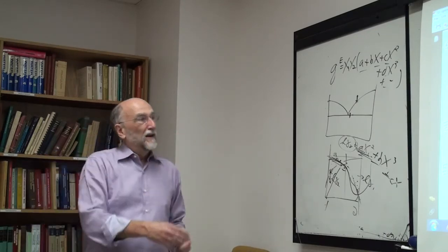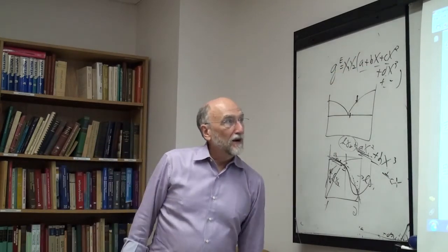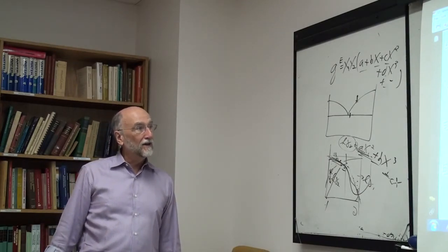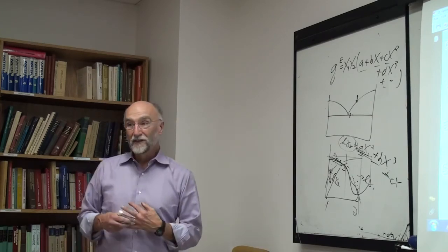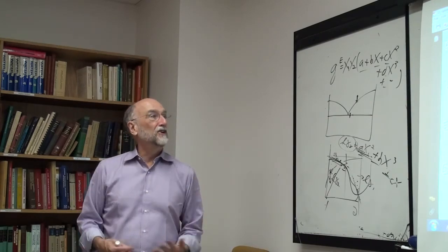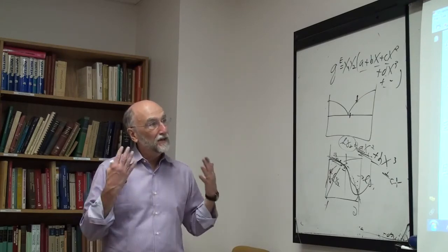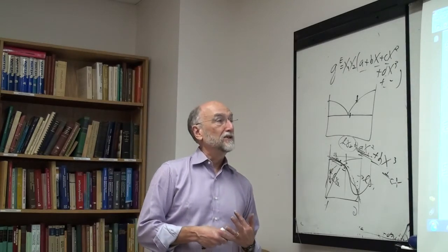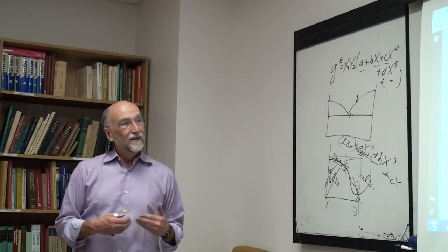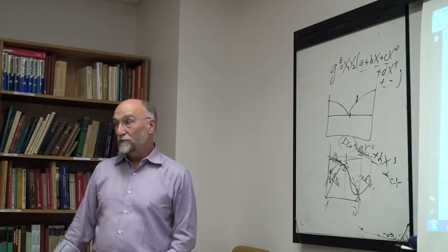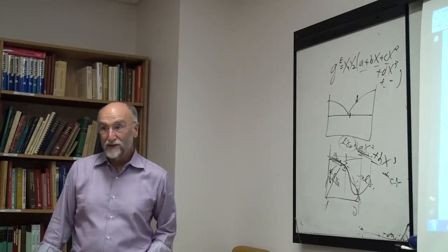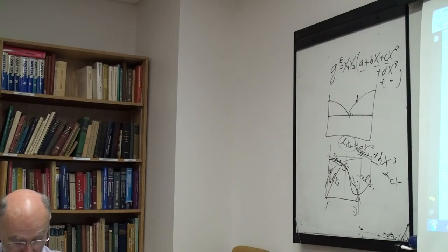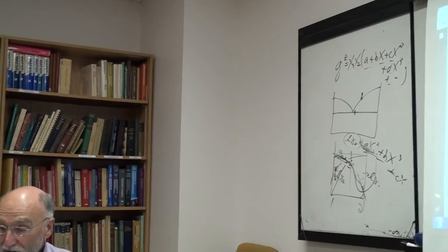So you're not really doing it. With least squares optimization programs like Parrot and OptiSage, you're not doing a mathematical minimum. You're not really doing a mathematical thing. What you're doing is assisted curve fitting. It's not a statistical analysis because there are not enough data points, and the equations we're using don't have the physical basis that they really should have. So it's not a statistical analysis, it's assisted curve fitting, but there's nothing wrong with assisted curve fitting as long as you realize that's what you're doing. And a lot of things we find in the literature, they don't realize that's what they're doing.